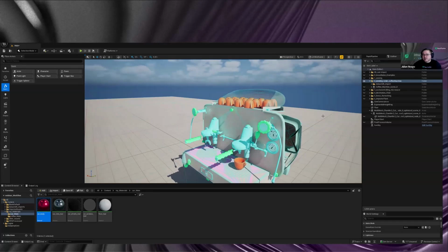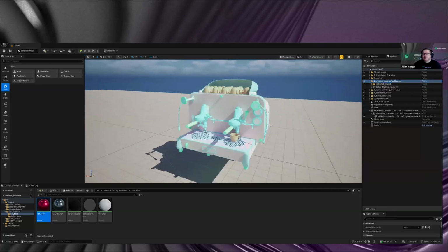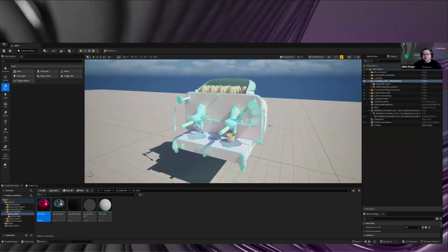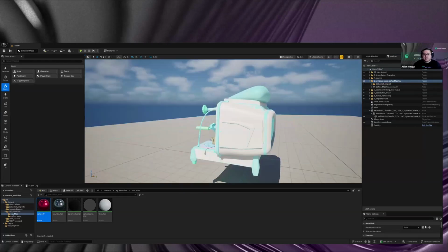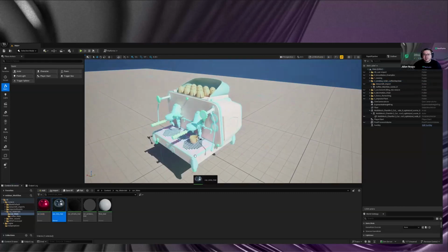As I showcased before, just a little check mark on the winding order correction, which was actually raycasting based. So it knows intricately what is inside, what is outside. It will correct the winding order. And then basically, let me see if I can activate it. So basically, this is the corrected winding order version. Again, it's not a perfect model, I would say, but it has now everything corrected, and we can start even assigning materials and going further with our workflows here.